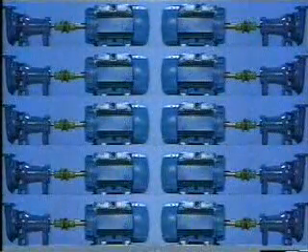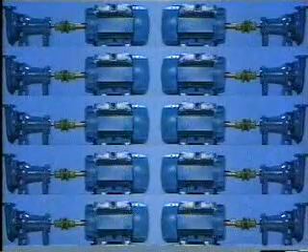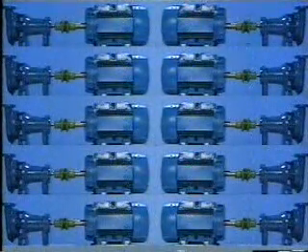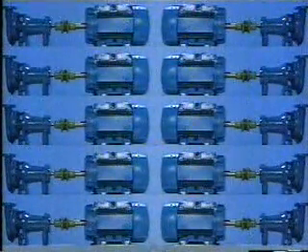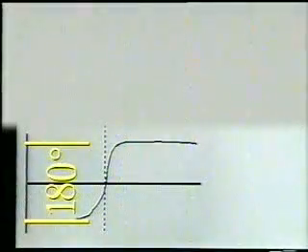This occurs because two systems are in resonance at the same frequency. A typical example is when there are several machines of the same type nearby, such as a row of identical pumps or fans. A coast down may indicate a good phase shift at a particular frequency, and we would expect a high vibration at the same frequency.